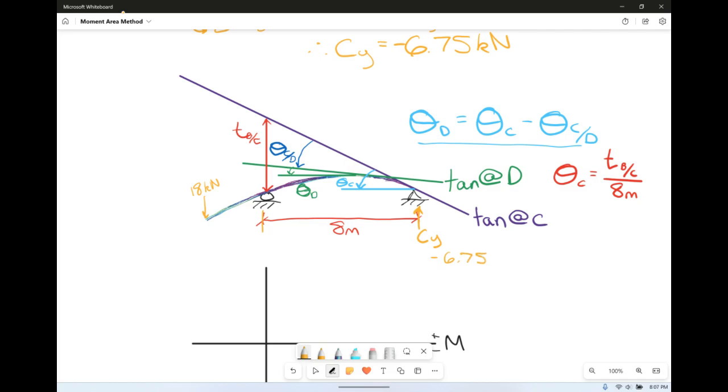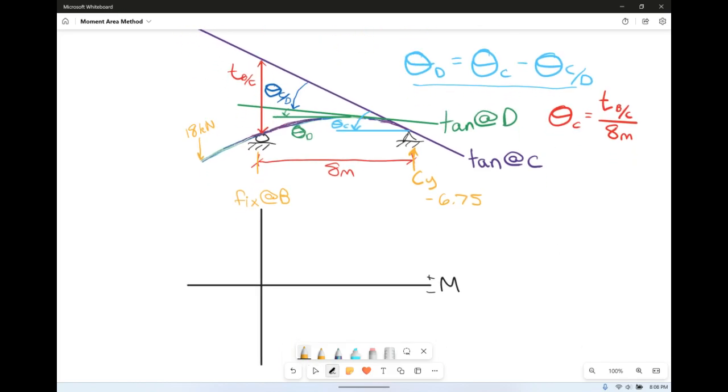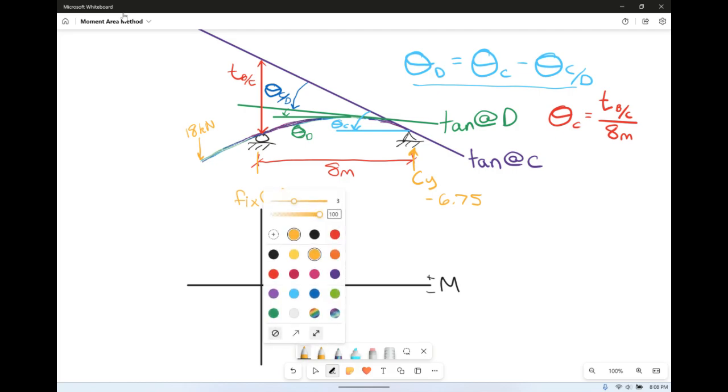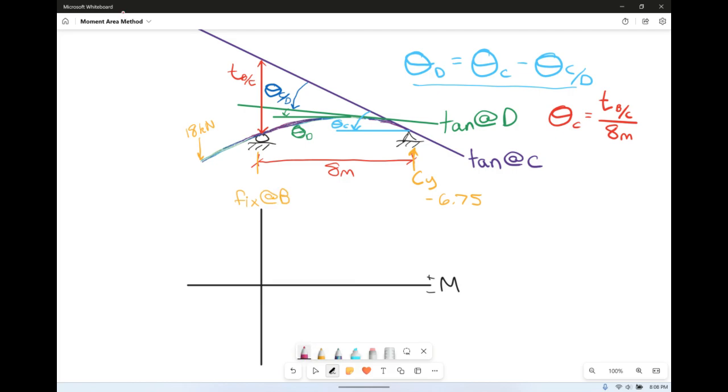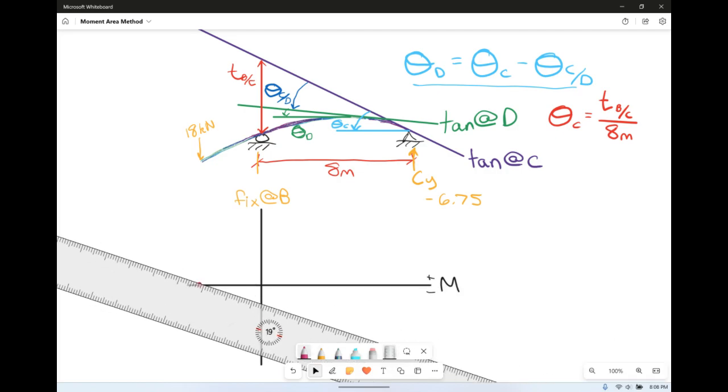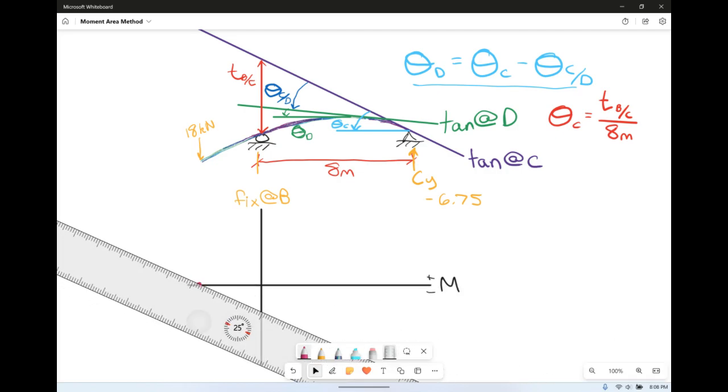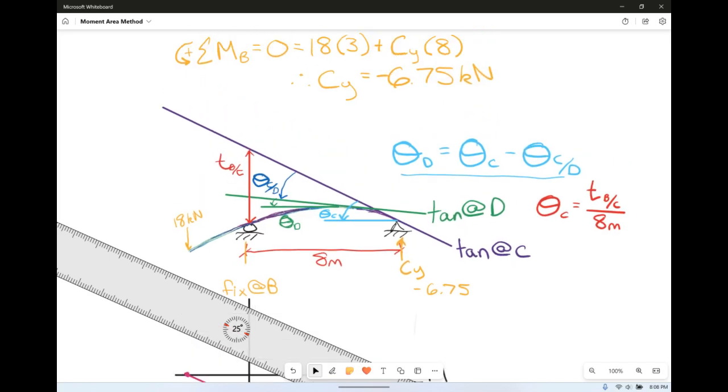So we're going to be doing the method of superposition, assuming that we are fixing at B. That's why I drew that line here vertically. So on our left side here, we're going to start at 0, where that point is taken at, and then it's going to go linearly down to P times L. Why P times L?